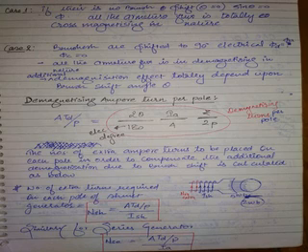Let us consider there is 5 Webers amount of flux coming out of a North Pole. Already there are, let us say, some shunt field turns. Let us say 5 turns are there. These 5 turns are producing 5 Webers of flux, which gives you 220 volts in the armature. Is it clear? That's the condition of the machine. On no load, there is 5 Webers of flux, therefore 220 volts is produced.